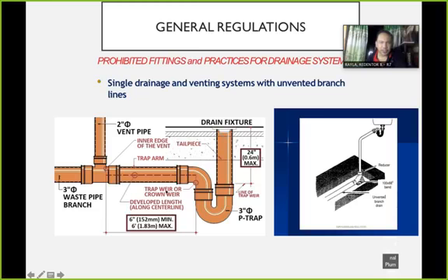So we have also a distance here from the P-trap to the vent, no? At least 6 inches minimum. No? So that is the minimum. You cannot make a line so close to the trap. So even the trap has a distance to the drainage, 24-inch maximum. So you cannot go beyond 24. No? It should be as near as 24.